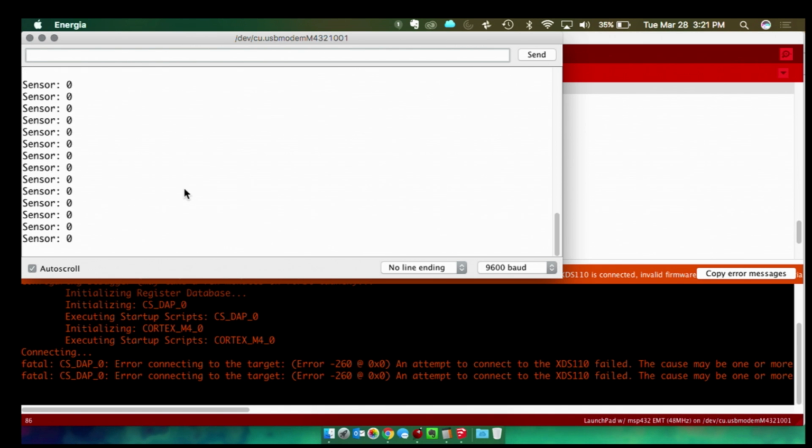As a stand-in for my moisture sensor, I have a little potentiometer knob here. I don't know if you can see it. And what I'm going to do is I'm going to slowly turn the knob, and we set the threshold to 200, right? So I shouldn't generate any phone calls until that threshold is met. And what I'm going to try to do, I'm going to put my phone on speakerphone so you can actually hear the message that was translated from text to speech in the cloud. So I'm going to make sure that I have speaker enabled and my phone is at max volume, and I'll hold it up to the microphone, and we'll see if it works. We'll give it a try.